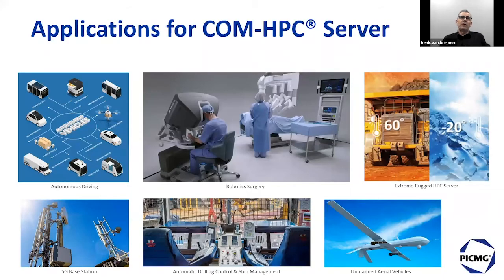Applications for COM-HPC as we see them. I think we separate three groups of applications. AI, obviously, what I already said, this is going to be one of the main drivers, and this is where we will see PCIe x16 GPU and FPGA connections for parallel processing. Since most of these designs will be multi-vendor, I mean, graphics and CPUs do not always come from the same vendors, we're basically talking about heterogeneous arrangements. And this is where the PCI Express bus speeds are very, very important.